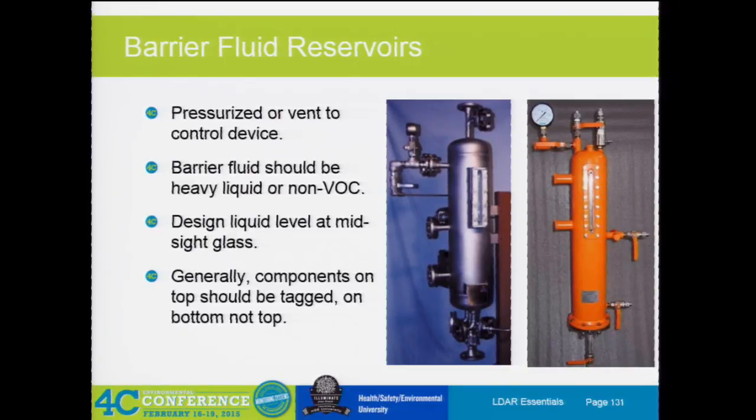Some people tag the top of those. I know I just left a place that had an argument that they don't tag the top of them. I would think if it's a light liquid pump, you'd have the potential for something to flow back through there. I don't think you'd ever get to 300 hours of in-service though. With your pressure gauges and stuff like that, I wouldn't think you'd ever trigger an LDAR applicable valve up there, but to be safe, you could tag it.